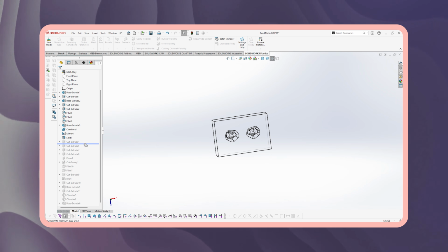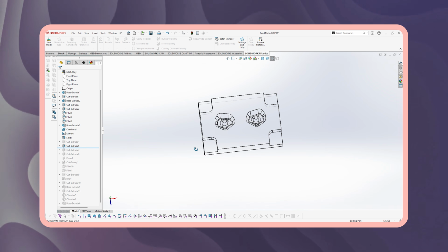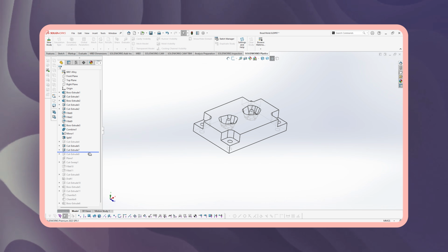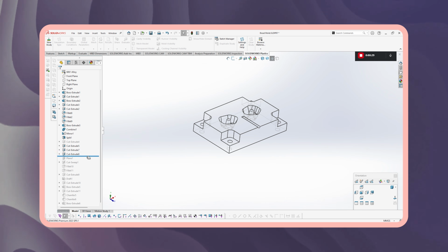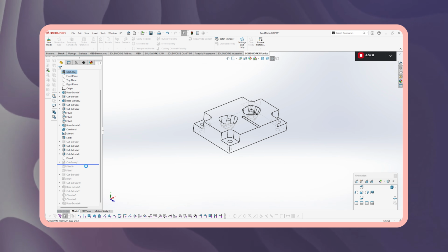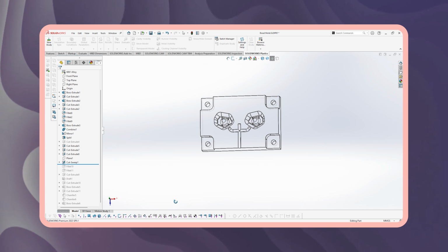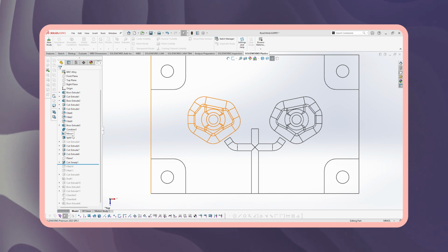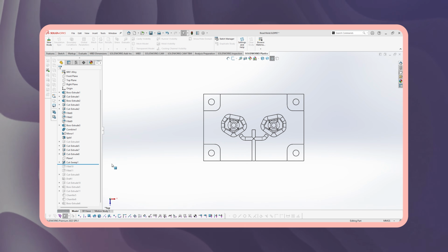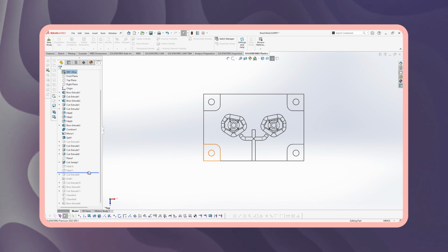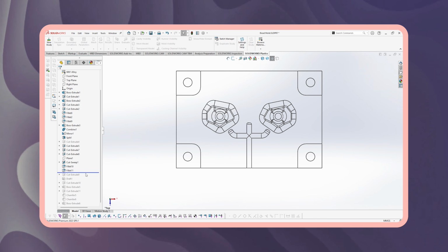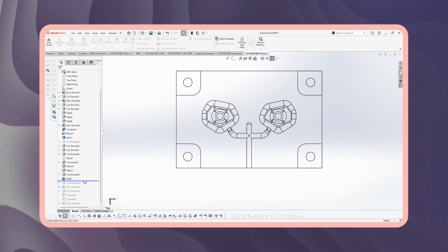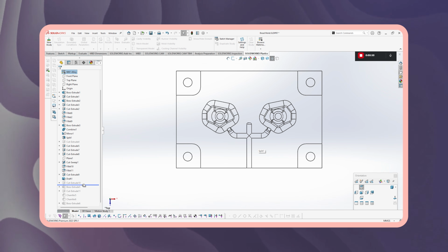Normally for a simple part like this, this method is enough. But for complex parts, we definitely can't get away with this alone. But today is our lucky day because this part is simple enough to make a mold like this. I didn't compensate for plastic shrinkage here because this isn't a critical dimension part. It's just a bead for a curtain. But if this were a functional part that had to fit with other components, shrinkage compensation would definitely be important.